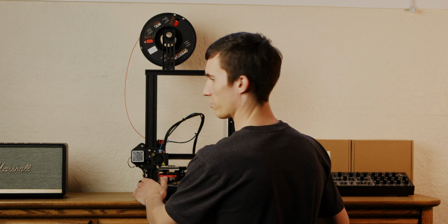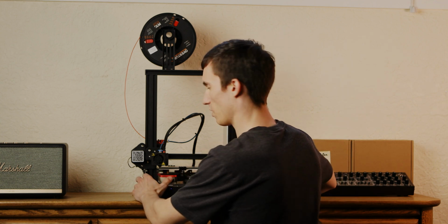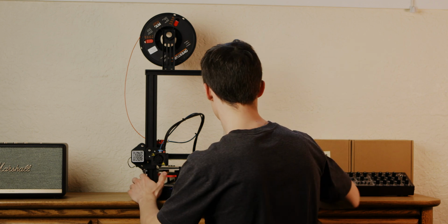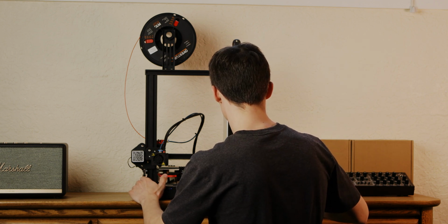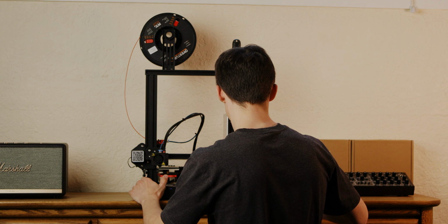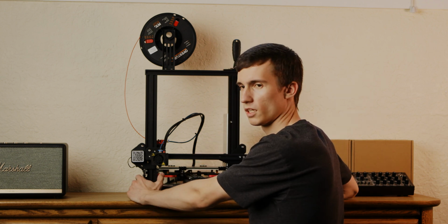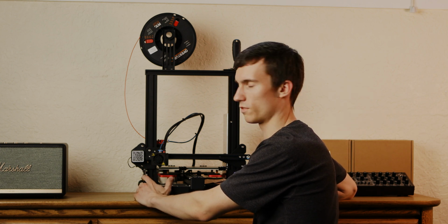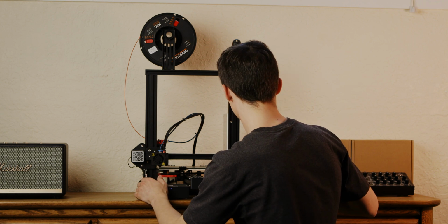So when you're bed leveling, the first thing you want to do is home all the axes, and that will pretty much bring it, most importantly, the z-axis to the point where it's going to start the print, or where it's going to reference as the 0 point for the z. And then once you're doing the bed leveling and moving around the x and y axis, you want to make sure your steppers are disabled so that they don't restrain you from moving around the different steppers.